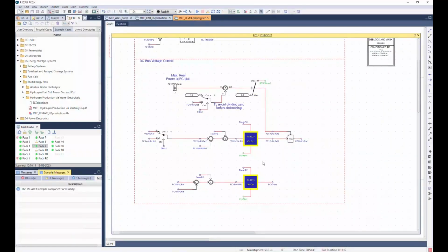A dual loop control scheme is used to control the boost converter. Outer loop of this scheme controls the output voltage of this system, that is the DC bus voltage. Inner loop of this controller controls the fuel cell current. This current control is required to prevent the fuel cell from exceeding its maximum current density. Output of the control loop is the duty signal to generate the PWM switching for the boost converter.